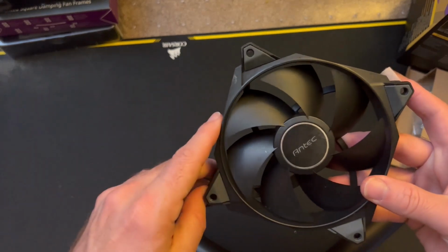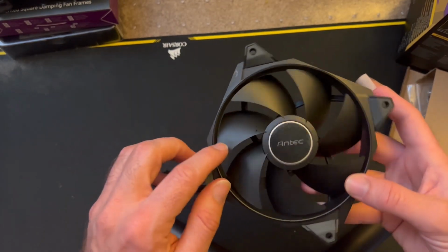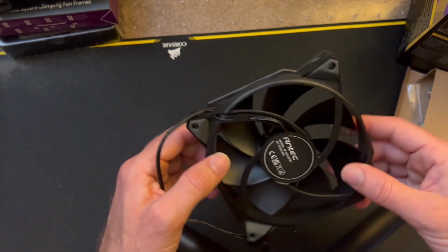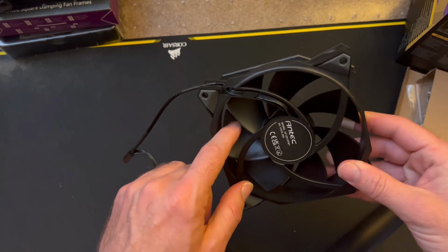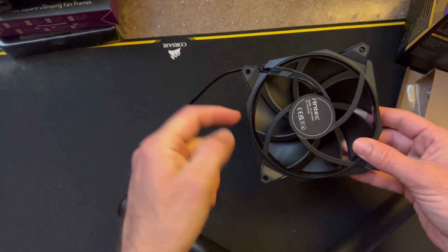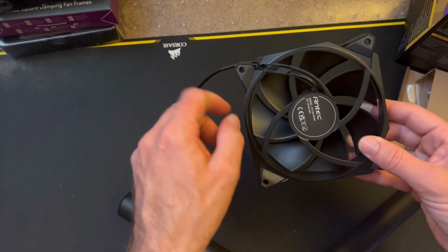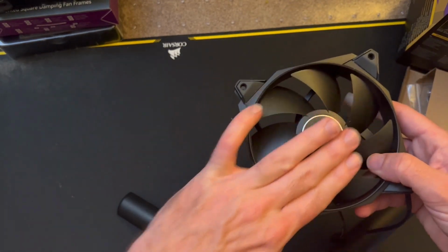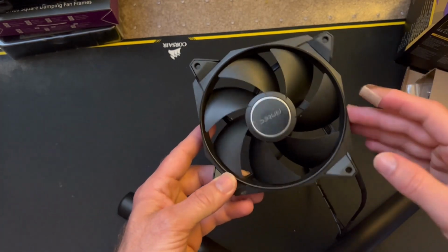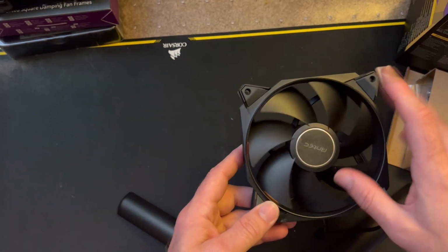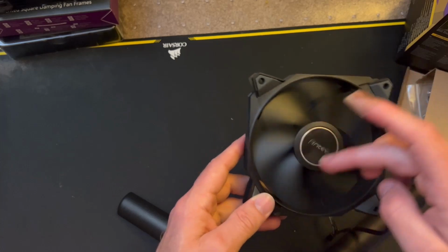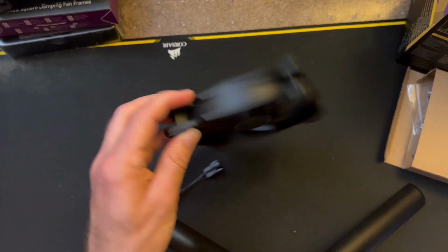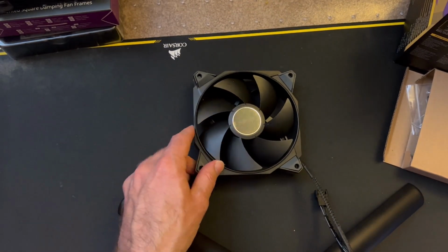In terms of the blade shape, they definitely are more of a pressure optimized fan, but they have a little bit of a hybrid flare. So that's having a little bit of a cup shape to it, which helps accelerate the air out the back of the fan while having an overall more flat appearance. So this would be geared basically as a pressure fan for a regular fit and thickness of the fan.